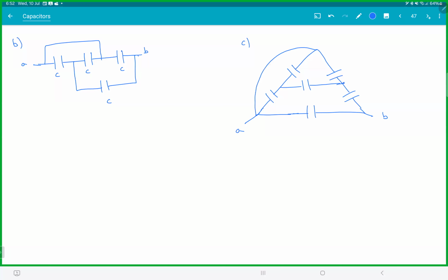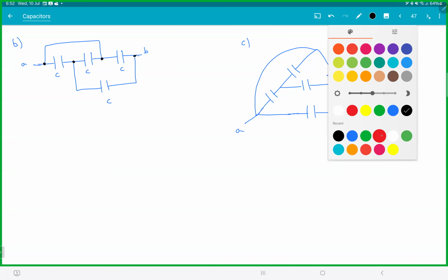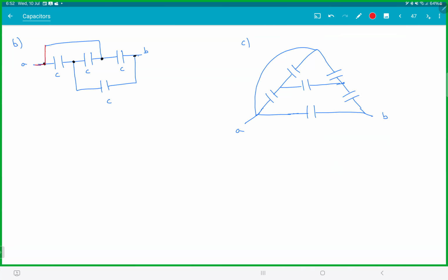This is your second technique, nodal analysis. First was series parallel. Again, remember step 1, see how many nodes are there. This is node 1, node 2, node 3, node 4. There are 4 nodes. Find how many unique nodes are there. Meaning if this is A, this entire wire will be A. Now if this is B, you're stuck. There is a capacitor here. Meaning no, that's not B, it is something else. So let's call this C. That's the idea. There should be a wire. There's no wire, na? There's a capacitor in the middle. So it is not B, it is something else. So let's call it some point C.